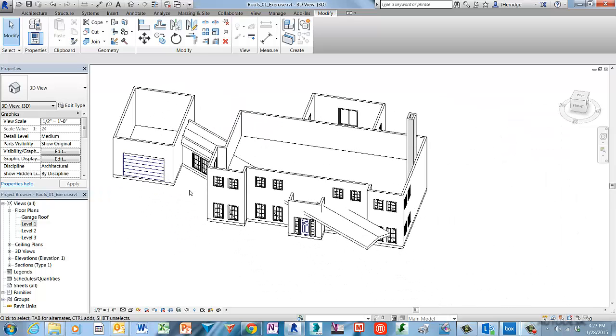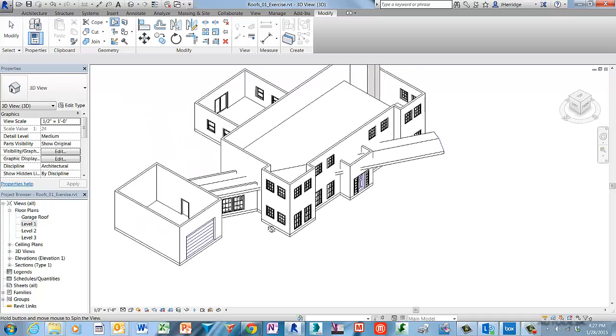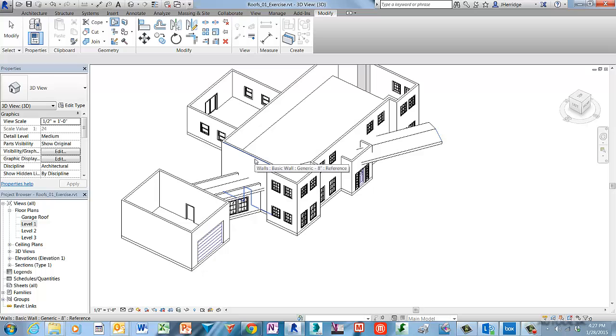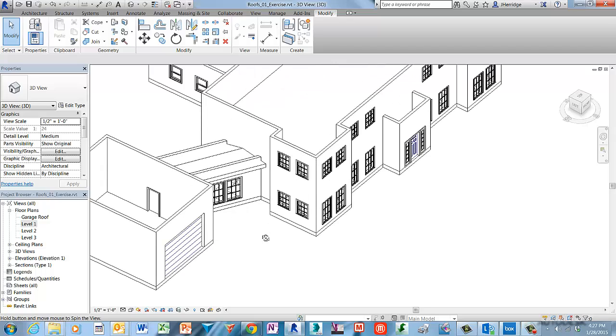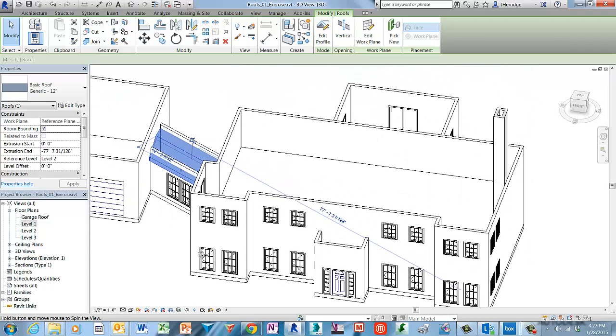Let's move over to the near edge and repeat the process again. So using the roof join unjoin tool again, select the roof edge, and then you'll probably have to use the orbit tool to spin the model around, and then select the projecting wall surface. So in this case, it almost acts like a cutting tool, and it cleans up that roof edge nicely to that wall boundary.